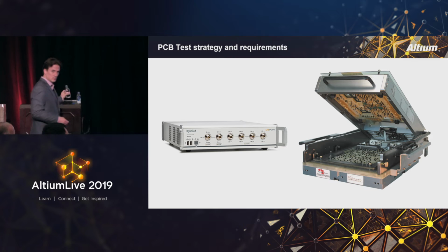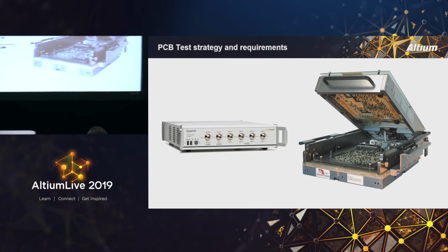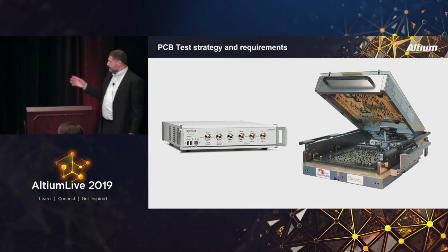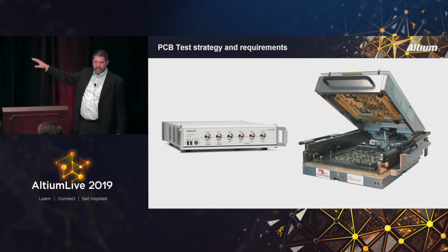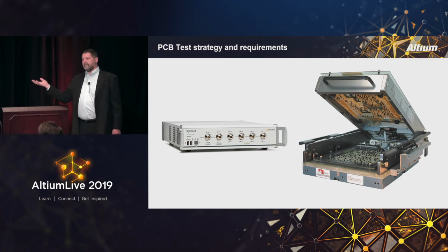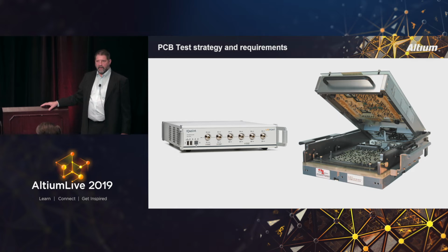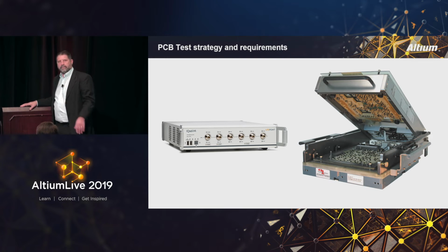When you're designing your printed circuit board for test, the number one cost adder is going to be doing a clamshell like shown here. If you can probe one side, that's going to be much lower cost. That's about 30 to 40% less.